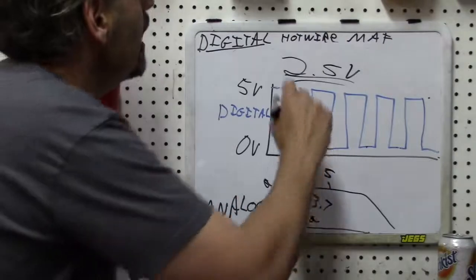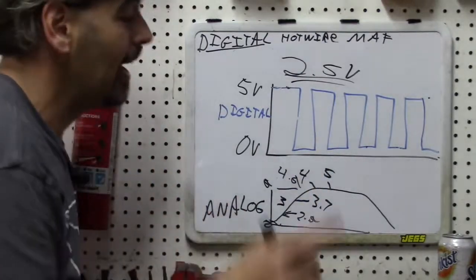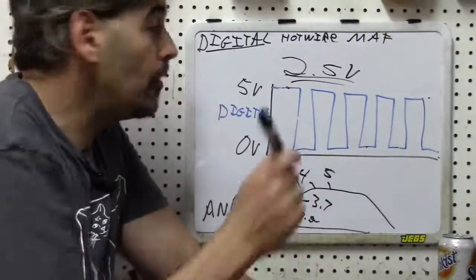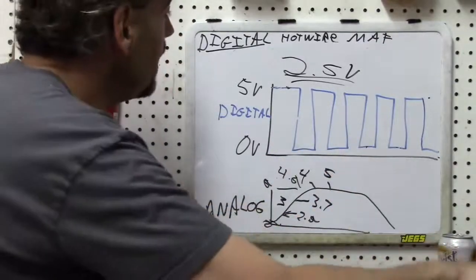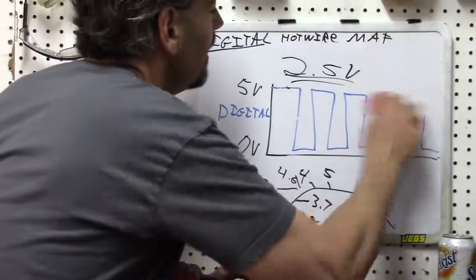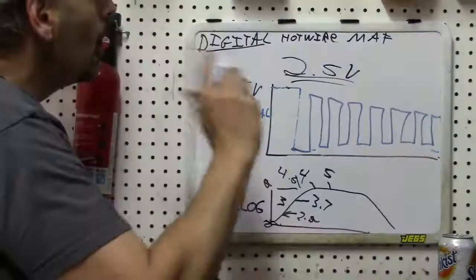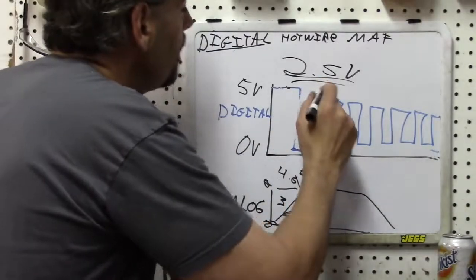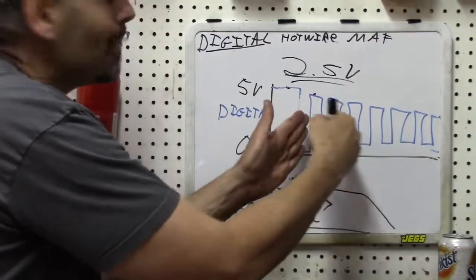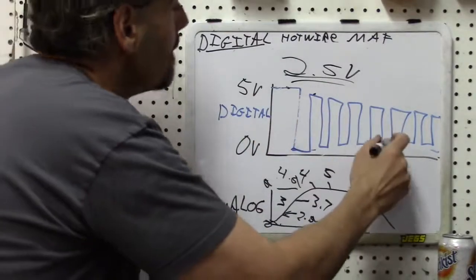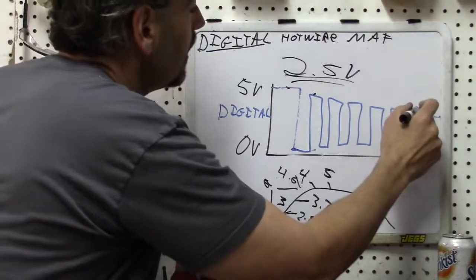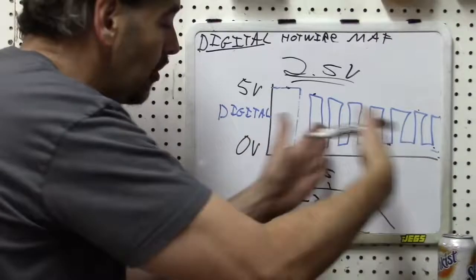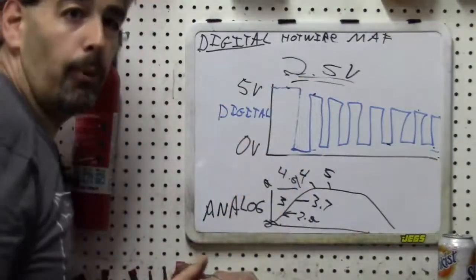That is for sure. It's going to show 2.5 volts. But the problem is that is going to be irrelevant to the frequency, because even if we increase the frequency, we are still going to have the same problem. There's going to be a lot more cycles between measurements now, but it's still going to do the same thing, and it's going to average out, even with the higher frequency, to show 2.5 volts.